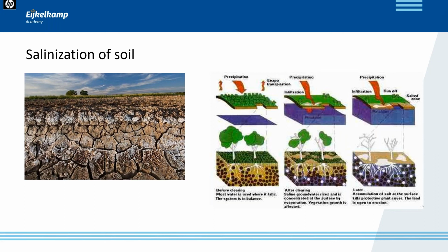The irrigated areas are subject to very heavy soil water losses through evaporation, and salts contained in the irrigation water remain in the soil and increase in concentration. Another working principle which contributes to salinization in soil is that with excessive irrigation, the groundwater level rises, more groundwater evaporates from the capillary zone, and leaves salts behind in the soil.